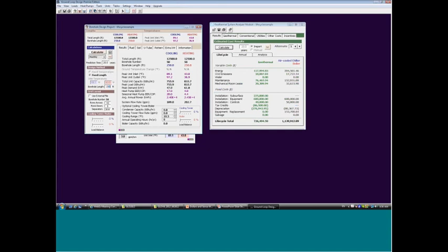Well, I'll do an extreme example. Let's say it's 400 feet. I'll do an extreme example to illustrate a point. So if it's 400 foot deep boreholes, what happens to the performance of my loop field? I got it. Now I understand the question. Okay, well, I'm going to answer this question that you didn't ask first, then I'll answer your question. You saw when I really bumped up the length to 400 feet, my temperatures are much more moderate, much higher performance, but my length has gotten a lot longer.